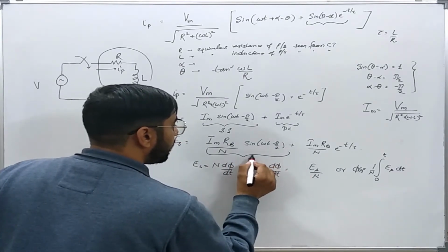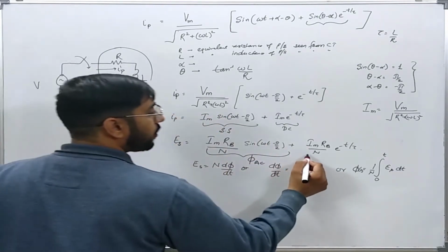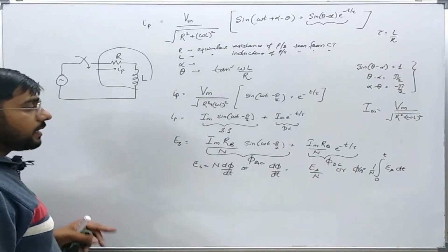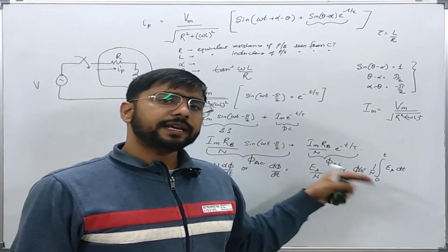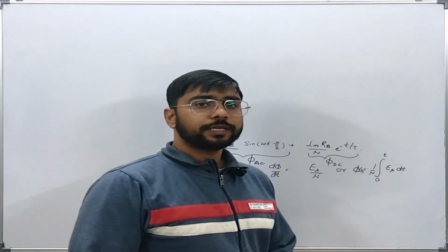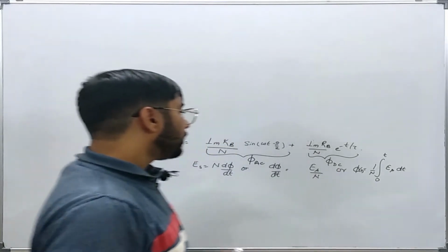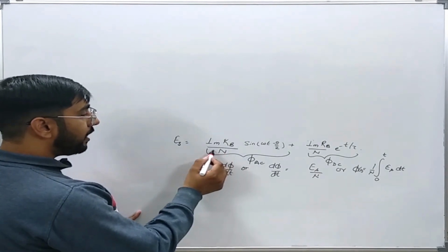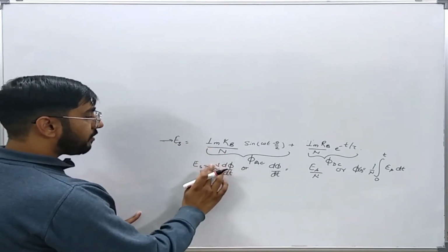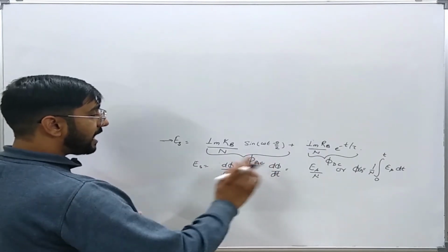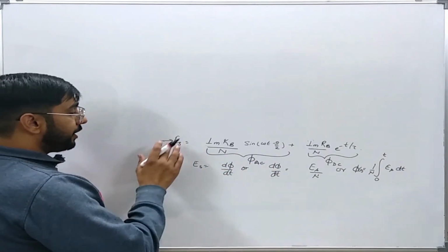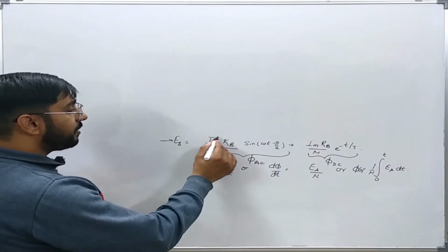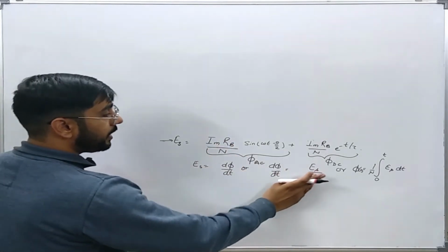Okay. Now we will find these two components corresponding to this part. There will be an AC flux component. Corresponding to this part there will be a DC flux component. Okay. Now we will do this integration in the next slide. Now let us do the given integration. There is one thing to note, that this N I have already taken care of while finding this ES. So there is no requirement of writing this N now, because I am just finding the secondary side induced voltage and the respective flux. Okay, so this N has already been taken care of, so no need to write here.